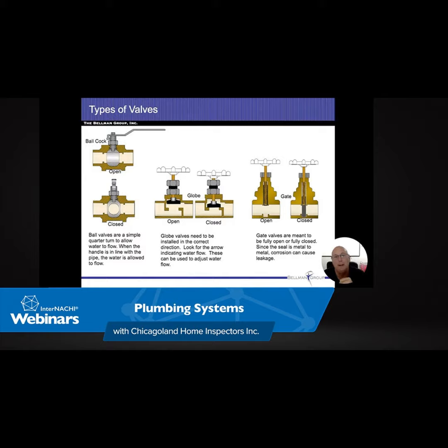The way we work our water systems in the suburbs is most of them are with water towers. So we'll have a pump that'll pump the water up into a water tower. And if you remember what I said about the elevation and the amount of pressure that's built up on those things, usually those things are about 100 feet in the air or more. So because of which, if we get 5 pounds for every 10 feet, that's going to give me 50 pounds of pressure as that water is pushing back into my water system. Not only that, but it acts as kind of like a bumper on a car, and it keeps any water from shocking as the pumps are running.